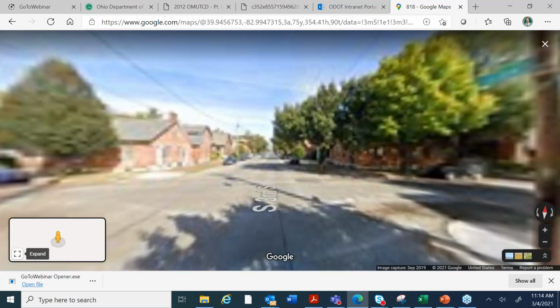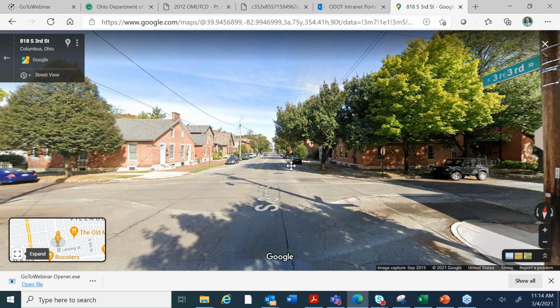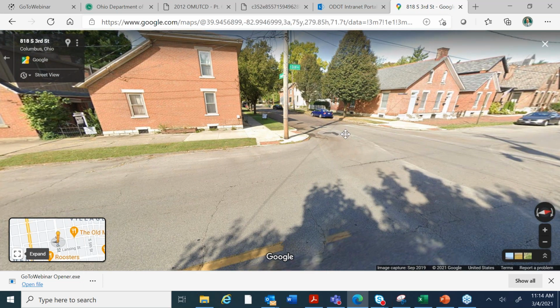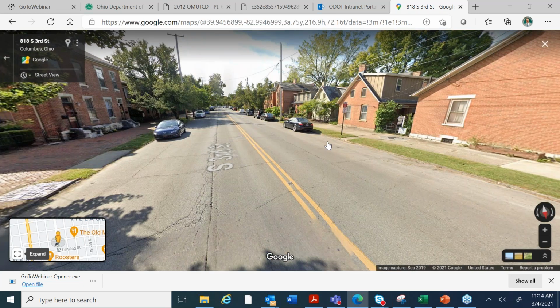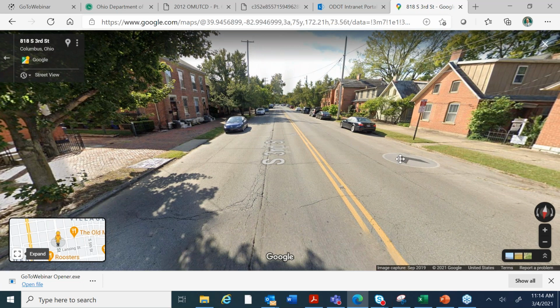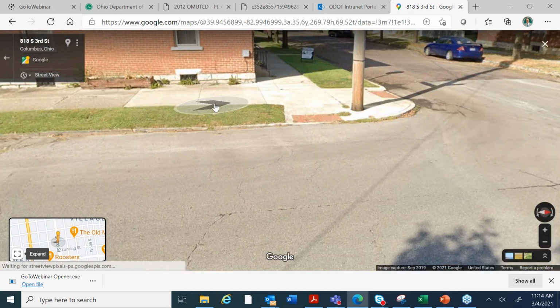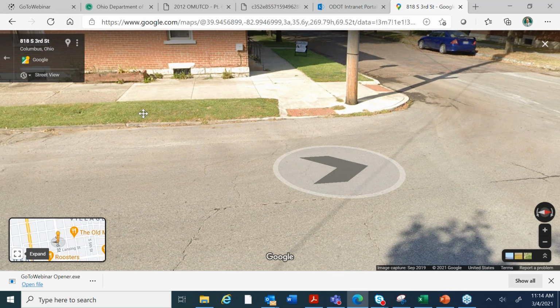So this really helps out as well in designing a work zone, because you get down here and you're on the street, so you know the details of what you have as far as the number of lanes, and whether there are good places to put your signs. Like it's always good to have a tree lawn between the sidewalk and the curb. It's always a good area to put signs.